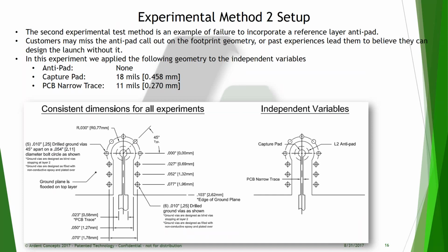Our second experimental setup was again something that we see our customers sometimes doing, and that is failure to include the anti-pad on the reference layer. So what we did here is we took our gold standard design with the best capture pad, best PCB narrow trace design, and best anti-pad design, and simply removed the anti-pad. And the results are as follows.